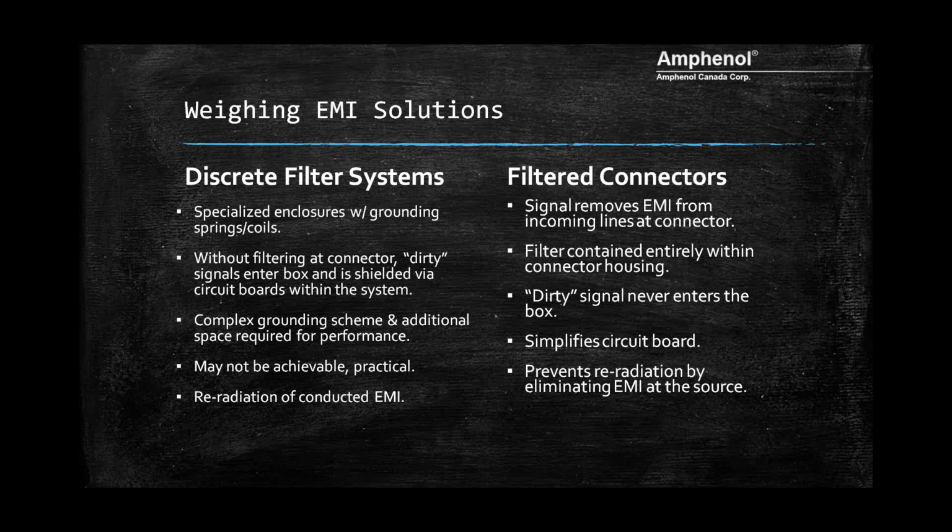So the dirty signal, quote unquote, never enters your LRU. It removes the need for any type of circuitry or mounting or any other type of grounding that you require, because the connector will be grounded to the chassis itself, and the signal gets attenuated right there at the entry point.